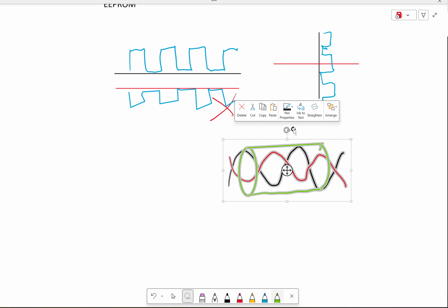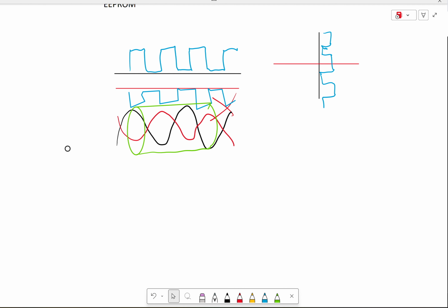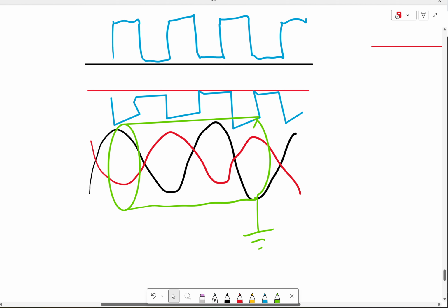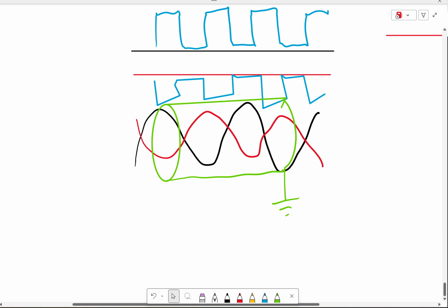So what that shielding does is, even if that twisted pair of wires was in close proximity to some other wires that had the rising and falling magnetic field, the shielding might have a little bit of current induced in it. But what we do is dump that off to ground on one side. If you ground your shielding on both ends, you just turn it into another conductor and it doesn't help at all. So shielding gets grounded at one end, and it goes around usually a set of data carrying wires in order to protect them from electromagnetic interference from other wires.